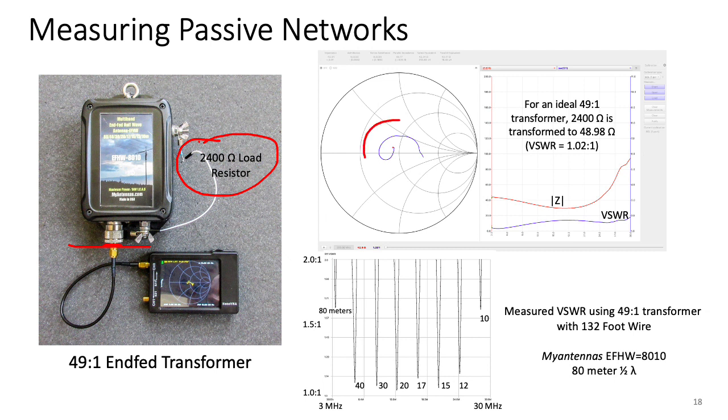As you can see, the SWR is floating around 1:1 or maybe around 2:1, and this is the location of the impedance values for that transformer transformation. Here is the actual plot of the magnitude of the impedance. This is 50 ohms here. You can see it falls a little bit below 50 ohms at lower frequencies, and then it moves up sharply on the high end. The standing wave ratio is still below 2:1, which is not bad.